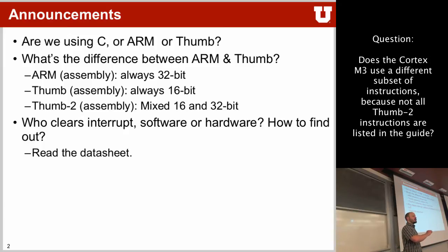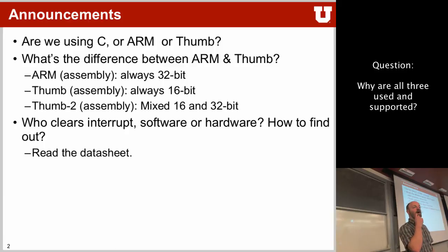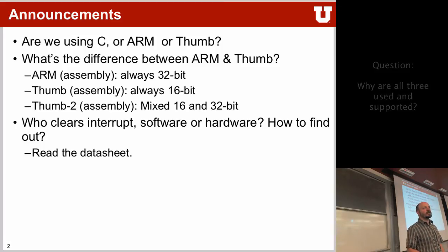What will happen is if you tell the assembler to assemble something for a specific architecture, so Cortex-M3, and if you use assembly functions that don't exist on that architecture, it will throw you an error telling you that this does not exist on the architecture itself. Yes? Why then does the ARM system that runs thumb2 also run the ARM instructions? Legacy. It's just there. Well, and the A series and application processors, yeah, the A series like the A9, A10, and so on, they all support ARM and thumb. And you have libraries that were compiled and written in ARM, and they're there, and you can use them and run them.